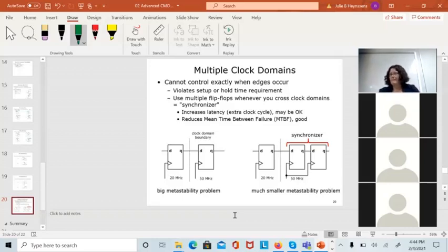That whole process took place in just 2 clock cycles. And there's an adder involved. And you know how slow adders are. And it's a 10-bit adder on top of it. Yeah, because adders are inherently ripple. The previous state depends upon the past state. The only way I could do it was to turn the 2 clock cycles into 4 clock cycles, which was basically using both a positive edge triggered flip-flop and a negative edge triggered flip-flop in the same system.